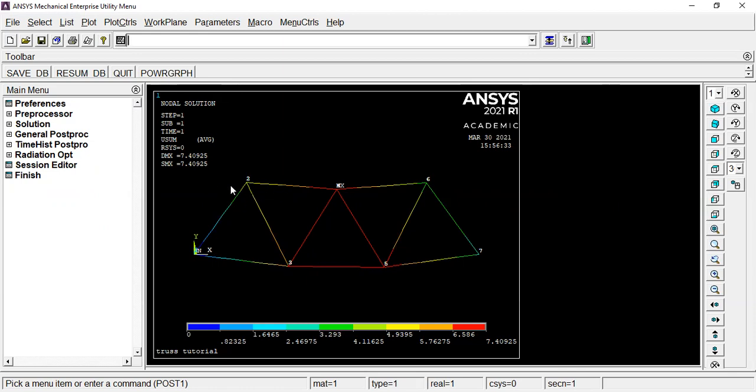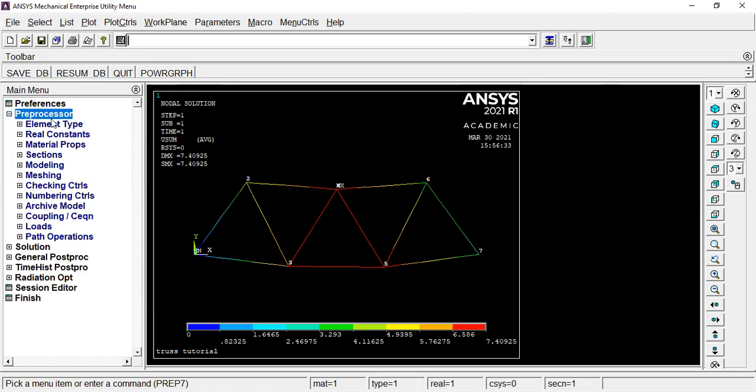Here this is the truss, and you have to find the nodal deflections, reaction forces, and stress. Here the Young's modulus is 200 gigapascal, and the cross-sectional area is 3250 mm square. So first you have to model this truss using the pre-processing phase. Then you have to add element type, real constants, the material properties, and meshing. So that was about the pre-processing phase.